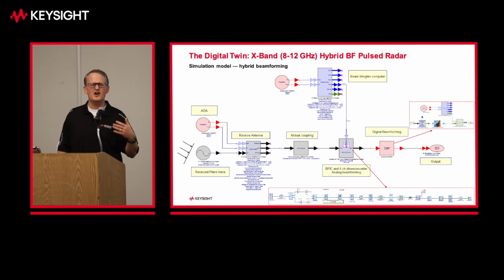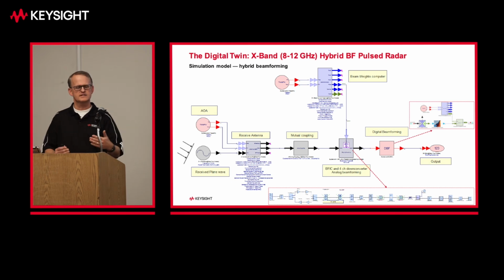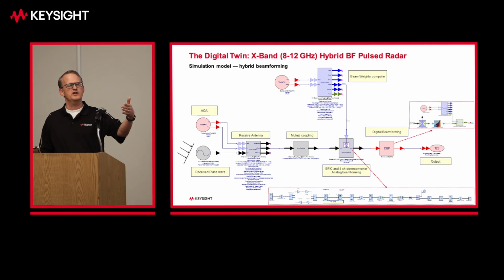The amplifiers. A huge thing now with these phased array systems is as you're blasting an array or a feed line or an active amplifier in an array, where you're scanning, the beam changes on where the load changes, right, based upon where you scan it. So this tool can take X parameters, some other models that Keysight has, like the dynamic gain model that you can measure on a PNA, and it actually takes load pull effects of an amplifier and can reflect those at the system level. And then I guess the S parameters, I already mentioned that.